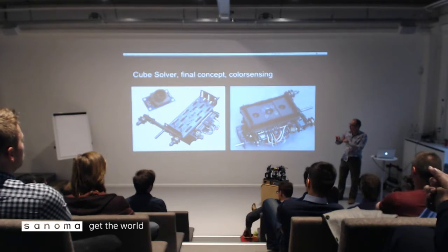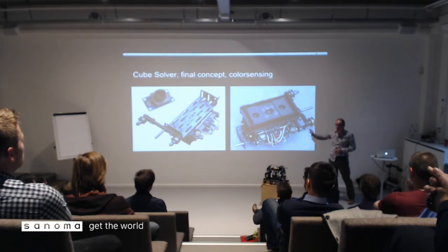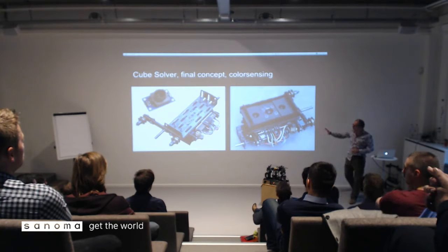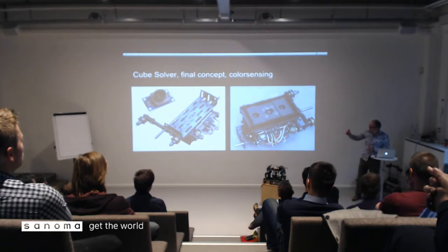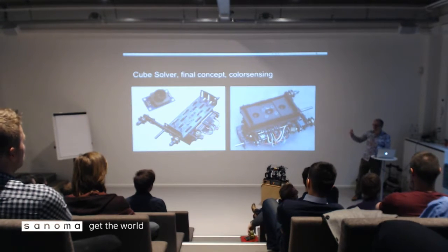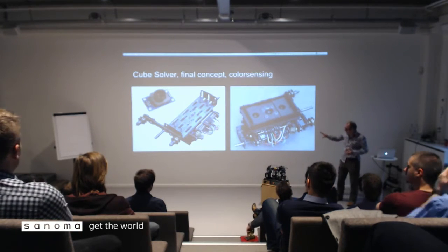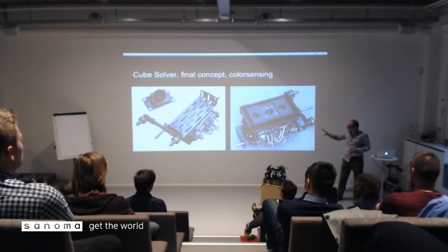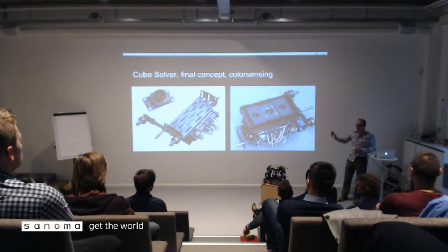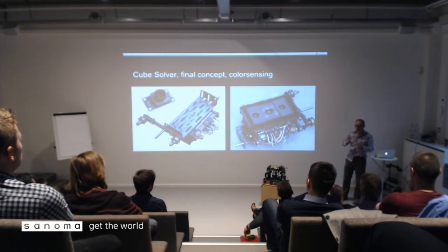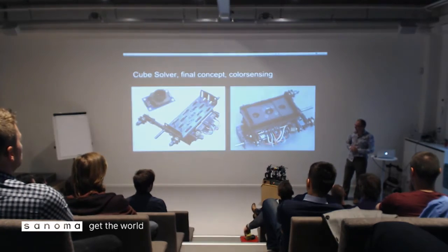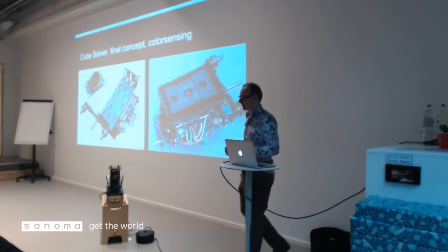I drilled a few holes in the circuit to get some extra pins to be directed to the Arduino mini board, because the Arduino mini board can get analog readouts from the color pal. Between the Arduino mini and the Raspberry, we used a logic level converter to make communication between these two boards possible. Of course, with the help of Maxim in this case.